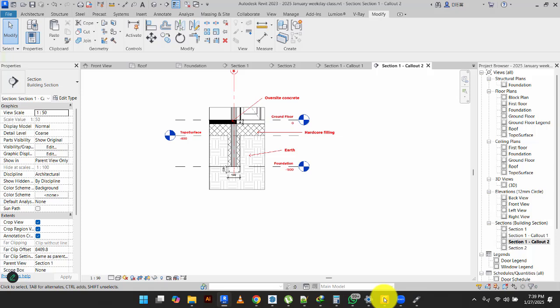So your client will tell you that the size of the land is 80 by 100. As much as possible, don't go by word of mouth. They may even give you a site plan, but please visit the site and take the dimensions yourself and be sure of the size.